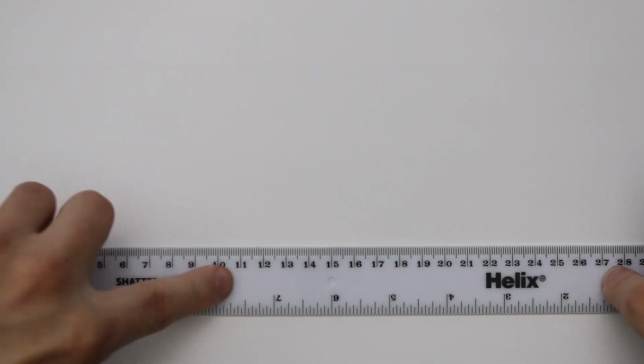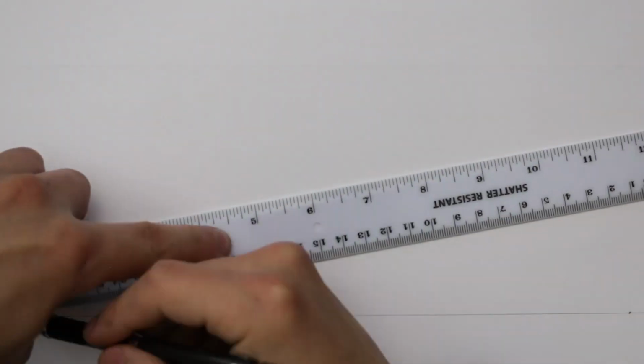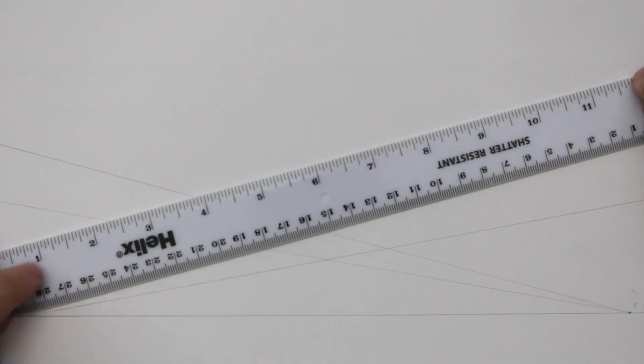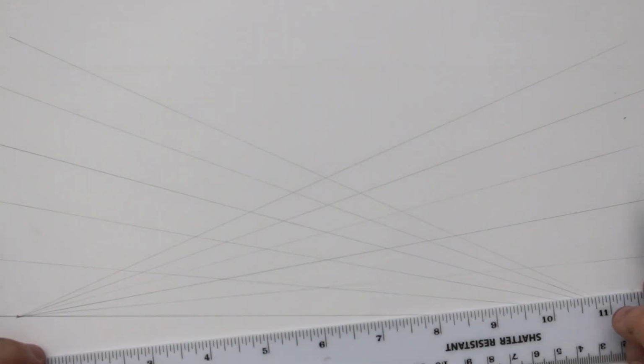So let's take a look at what to do when that third vanishing point is off the page. Also, in a future video, I'll cover what to do when all the vanishing points are off the page, but for now, let's look at a 3 points perspective grid. So let's start off as usual with the horizon line and 2 vanishing points that are apart. Now I begin to cross some lines that extend from those vanishing points, and this is just to guide me when I start drawing in perspective.